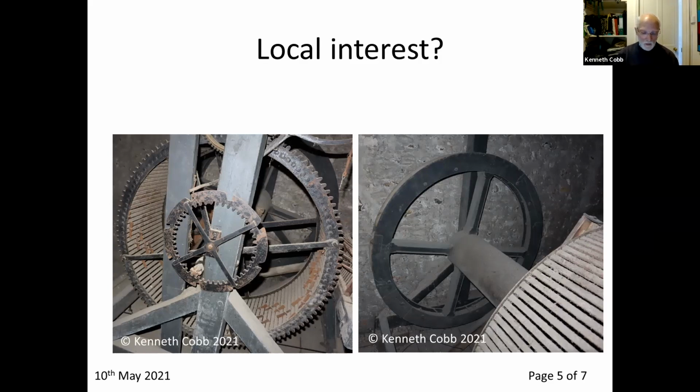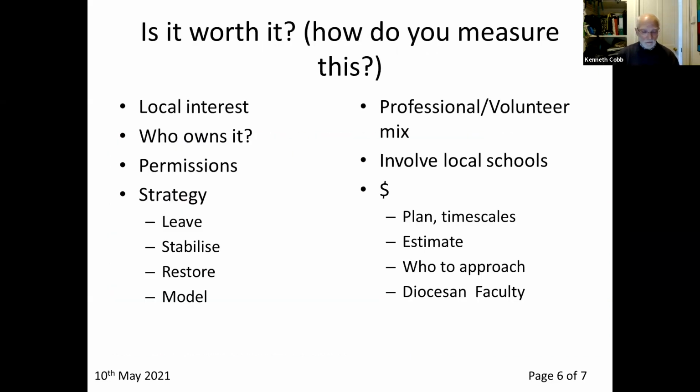I assume the wheel next to the wall was used to wind the tune wheel, using a looped rope that enabled winding to take place in a more accessible room lower down the tower. Note the condition of the remaining parts is satisfactory, in that there is some corrosion to the iron components and little sign of woodworm in the wooden framework. I can rock the tune barrel, indicating its bearings are not jammed solid.